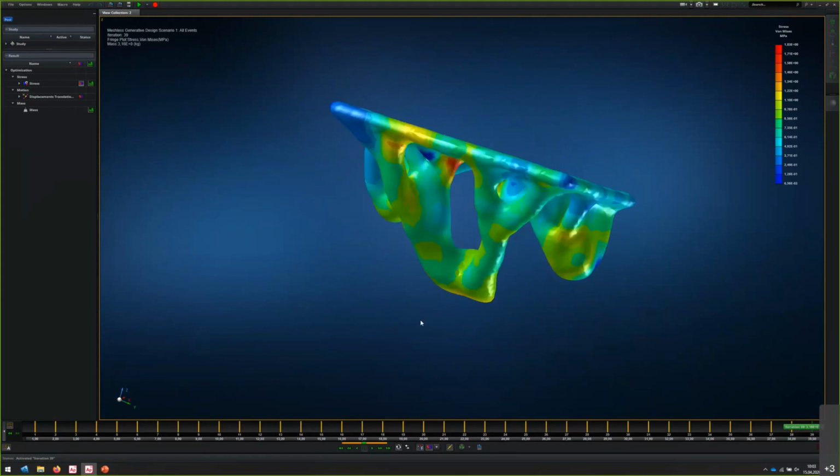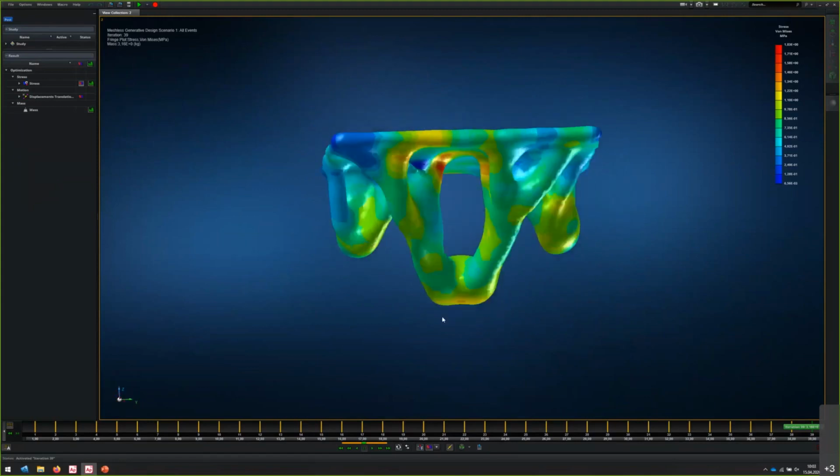Yes, I think we should stop very soon. There's just a very new question of material database. You should always set up your material by yourself, but as Anne has shown, it's mainly important for the optimization. It's just the Young's modulus and the Poisson ratio, and then as well the maximum stresses.